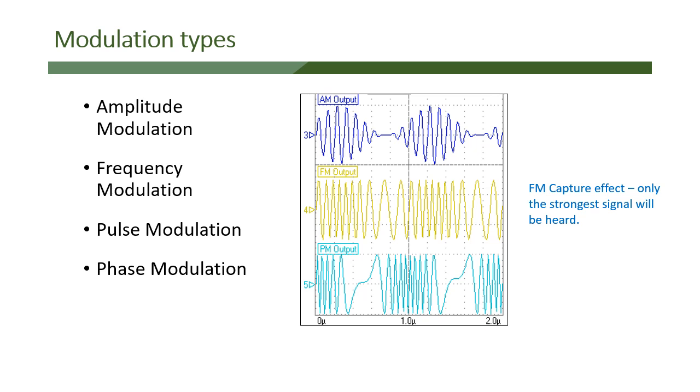Because the radio is looking for an amplitude modulated wave, you will be able to hear static crashes on AM. You'll hear certain types of man-made RF noise on AM because the radio is optimized to listen to changes in amplitude, and that's where man-made and also natural RF noise generally occur.